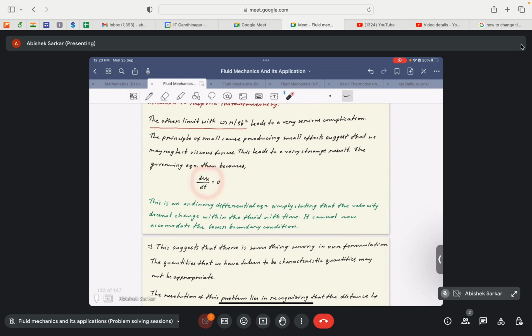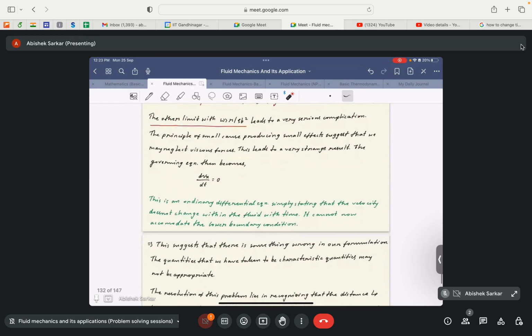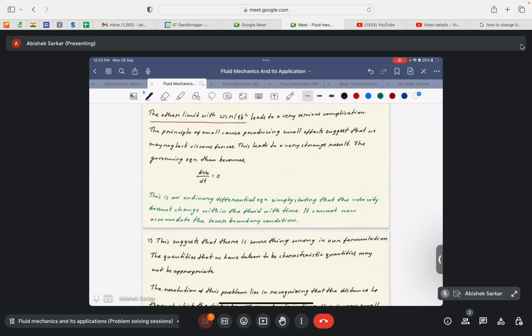Why? Because it's not able to capture the fact that the lower plate is oscillating. Let me try to show you. There are two parallel plates, and the lower plate is oscillating with some certain time period. But what this equation tells us is that the velocity profile we will get after solving it is this. So even though the plate is moving, this equation tells us that the velocity profile would be of this form, which is not the case. It is not possible, right? So it essentially tells us that our governing equation itself is wrong.